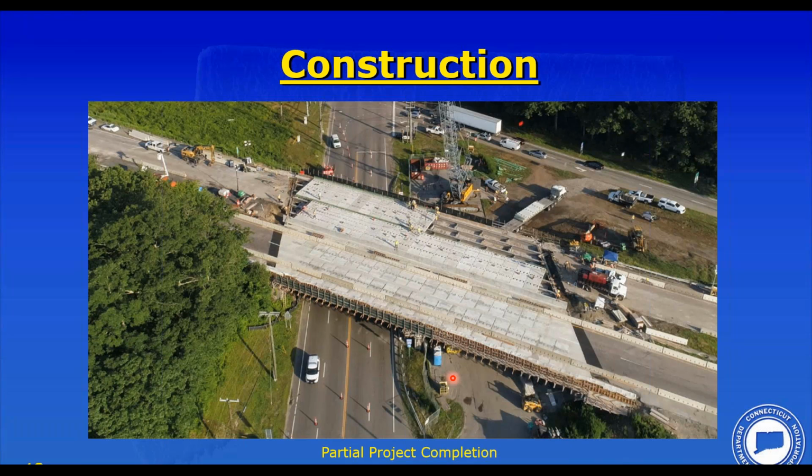As far as replacing, as Tim mentioned, modular deck beams with two steel beams and a precast deck are very popular. As you can see, looking at these details, the connection of a precast deck to a beam to get composite action is a significant connection. And the other thing we look at too, the cost of painting steel beams is quite high, and sometimes it's actually less expensive to replace the steel than it is to paint it.